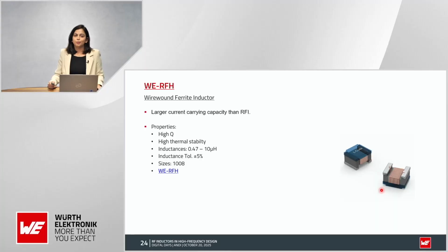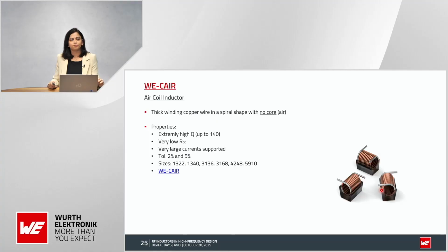Then comes WE-RFH. It has larger current carrying capacity than WE-RFI. It also comes with high quality factor, high thermal stability, and inductance that goes from 0.47 microhenries to 10 microhenries. Inductance tolerance is plus minus 5%, and the only size available in this series is 1008.